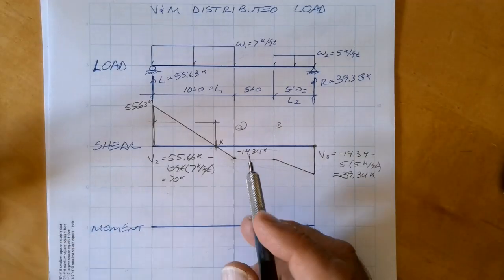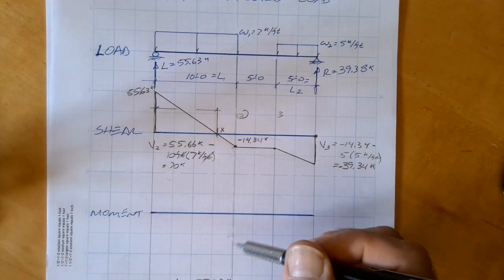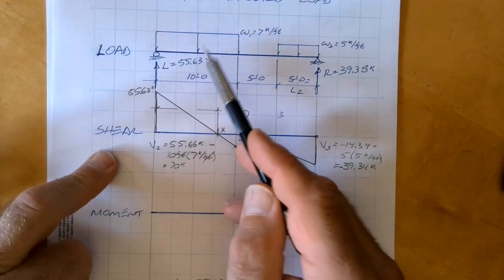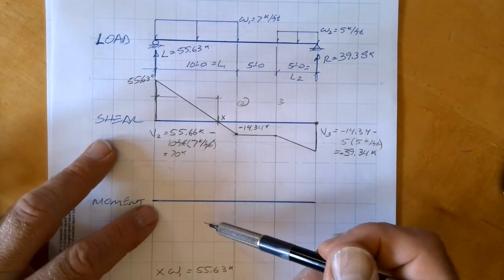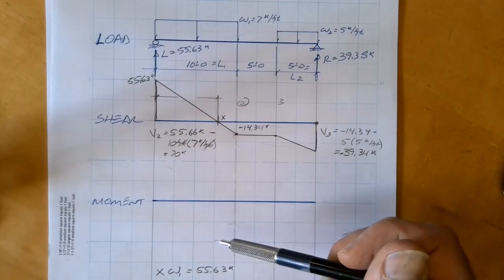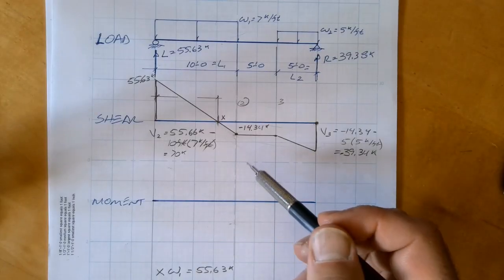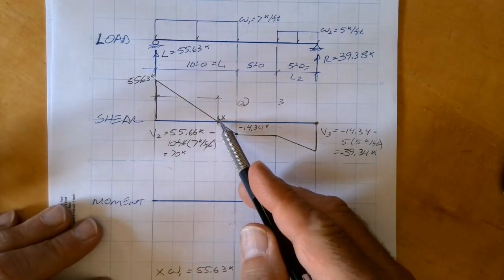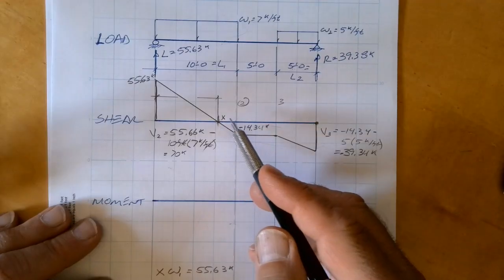Okay, so now we're going to look at just a few points on this moment diagram, because going from a triangular or a rectangular load to triangular gives us a parabolic load, and it just gets harder and harder to solve as I go. So let's just look at some discrete points on this. The maximum moment is going to occur where the shear diagram crosses 0.